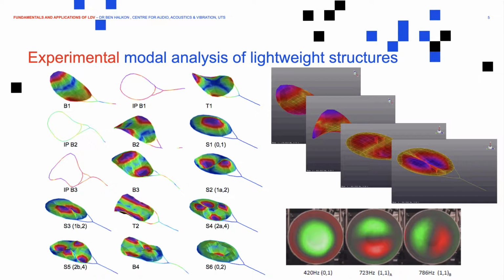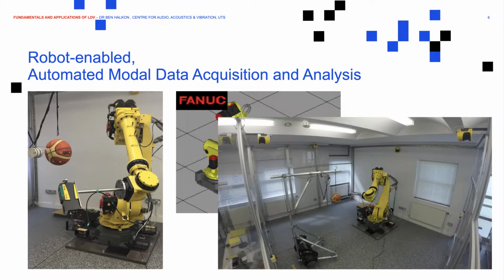Here are some other examples with relatively high spatial resolution of some Malaysian gamelans, which is a type of gong, and we made these measurements to fit to numerical or analytical equivalent measurements or predictions of the vibration frequencies. You can see the fundamental mode that's like a diaphragm type mode, and then a pair of diametrically opposed second order, second bending modes.